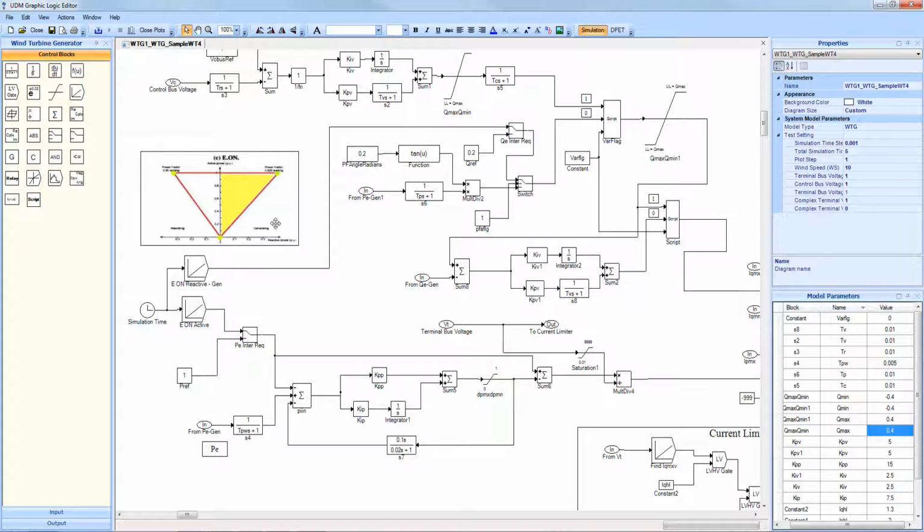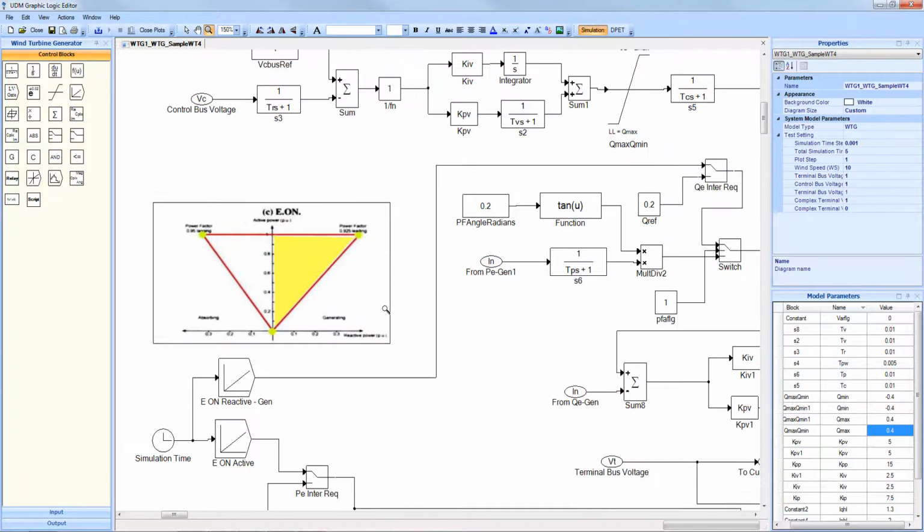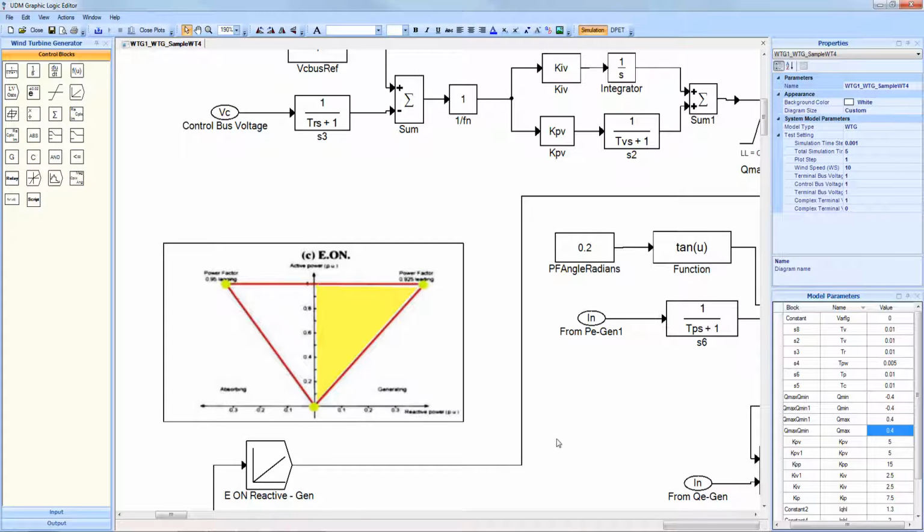So now we can proceed to run the highlighted portion in yellow of our interconnection requirements, which will start to inject active power from 0.2 per unit and finish at 1 per unit, or 100% of the wind turbine generation capacity, and it will observe whether we can meet the total full load demand reactive power of approximately 0.4 per unit.